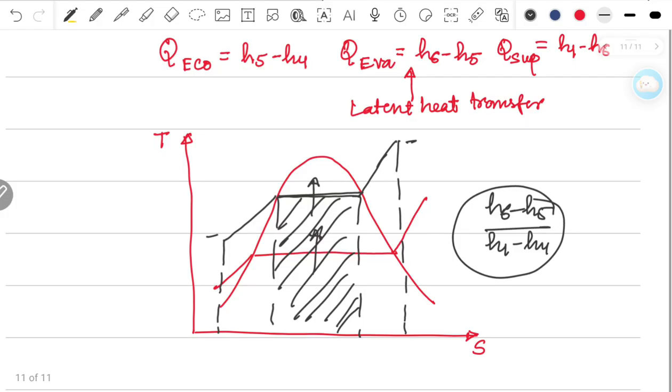You must also know that there are power plants known as supercritical power plants. There you won't have this phase conversion zone. Directly there will be liquid, and after this point there will be vapor. So there is no phase conversion zone. Only a portion will be there which is called the separator, which works during the starting phase. So this is what will happen.